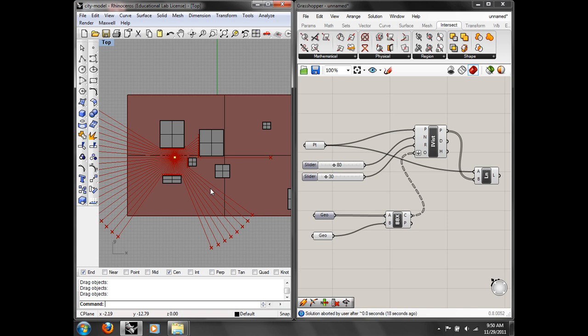Okay. And I'm not going to do it because it's going to take a little bit of time, but if you know your data structures, you could draw a line of a person walking through the city, and then you could distribute points along that line, and you could draw isovists from each point on that line, and you would get what a person would see as they walk. Okay. You just got to manage that, because then it's going to get a little bit complicated. So there's going to be some grafting involved with that. Okay. But that's the general idea.